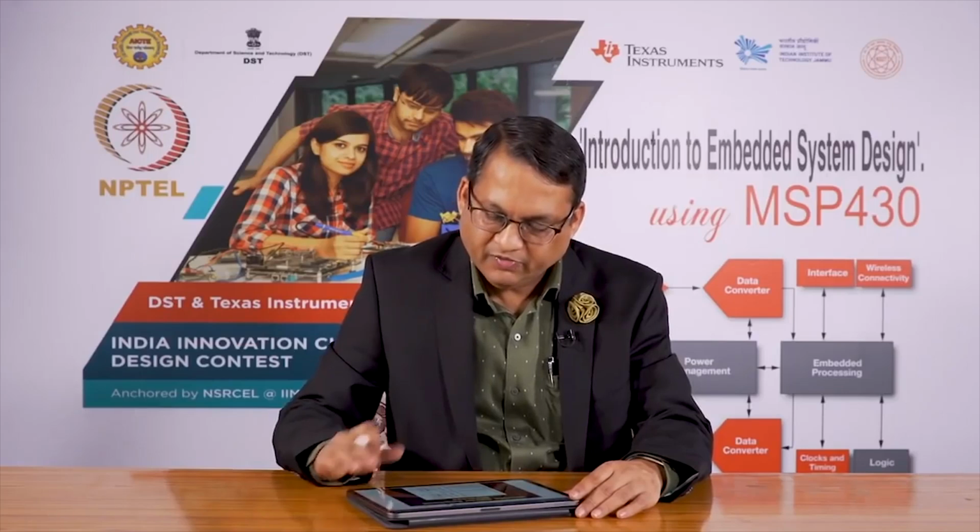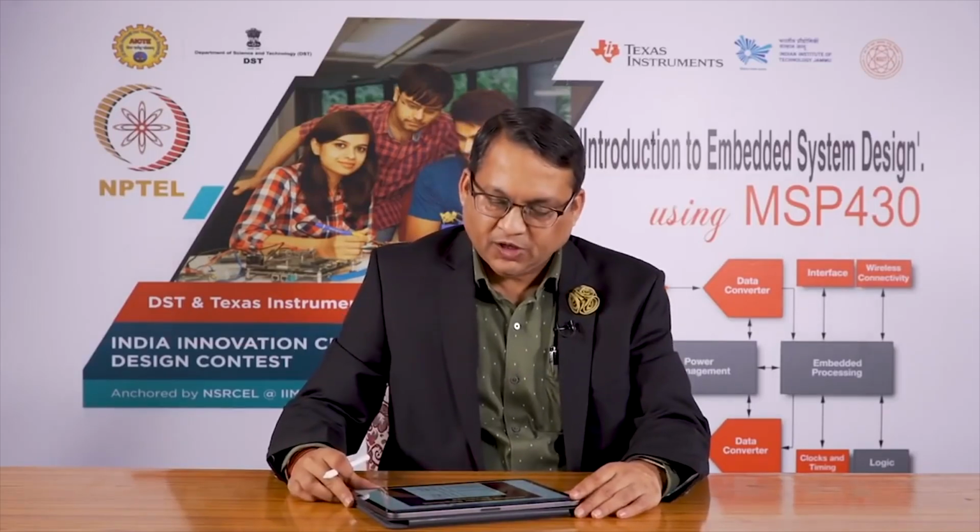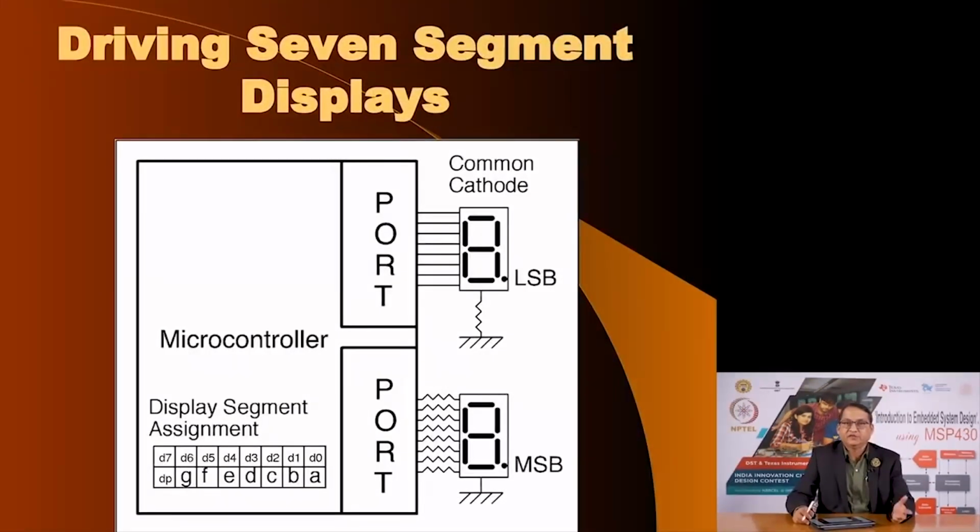Here is another variation. Now, you may wonder, instead of connecting using 8 resistors, can you use a single resistor like this, and this way you can save 7 resistors? Well, this may seem like a good deal, but this will give you unequal intensity of the LEDs. Now, imagine that you want to turn on only one LED out of these, maybe you want to just display a bar. So, this particular LED you want to turn on.